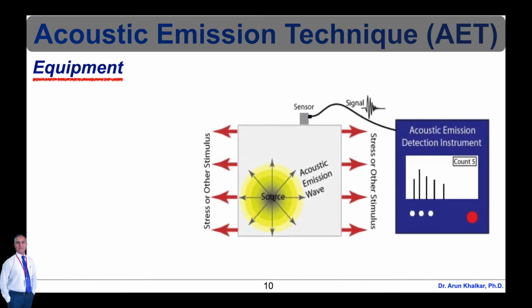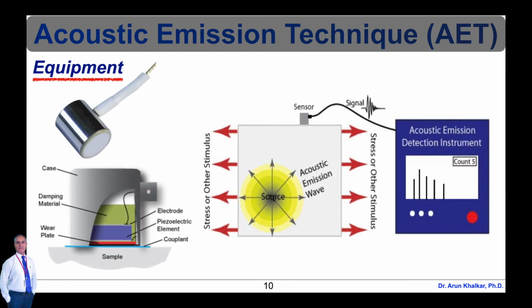Acoustic emission testing can be performed in the field with portable instruments or in a stationary laboratory setting, as shown in this figure. Typically, systems contain a sensor, preamplifier, filter, and amplifier along with the measurement, display, and storage equipment, that is oscilloscopes, voltmeters, and personal computers.